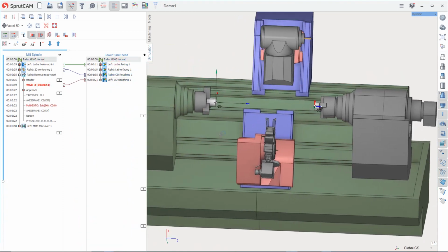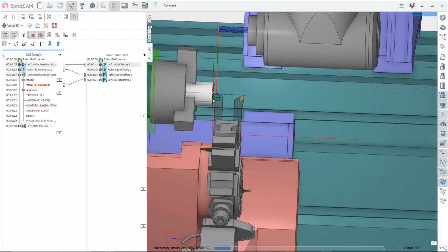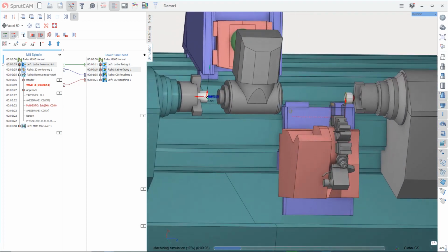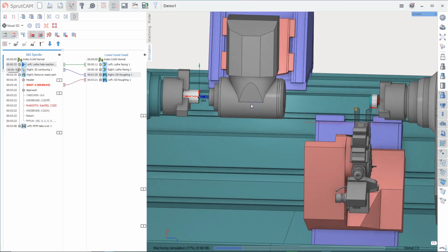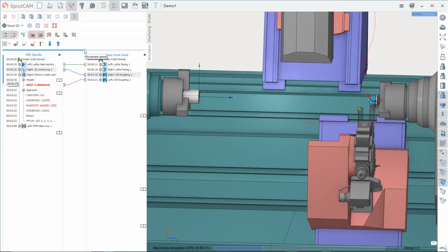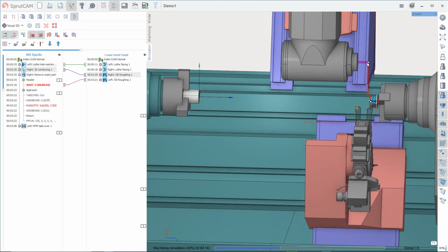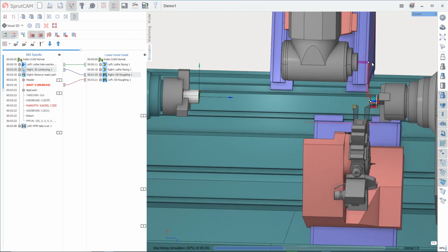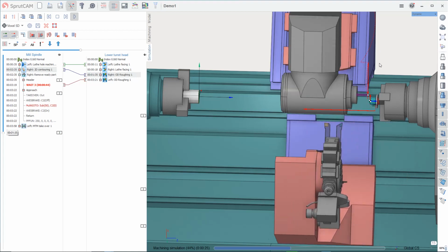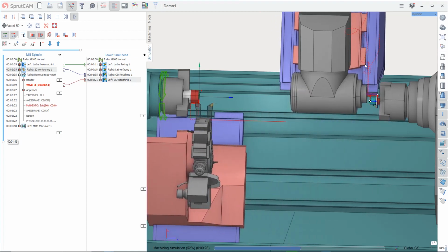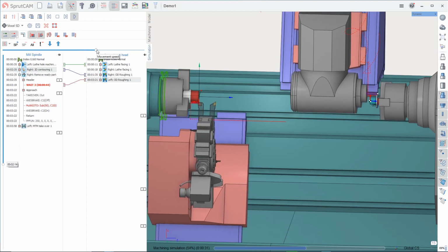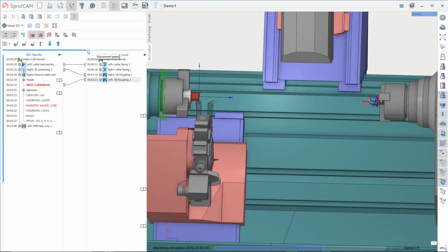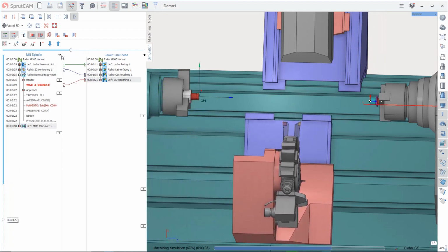Reset workpiece and try to do it. Waiting here. Okay, it waits quite a long time, so we can reduce the feed rate for the drilling, for example, to optimize the tool lifetime. Okay, after that, profiling and 2D contouring, and in the end, finish this one and take over.